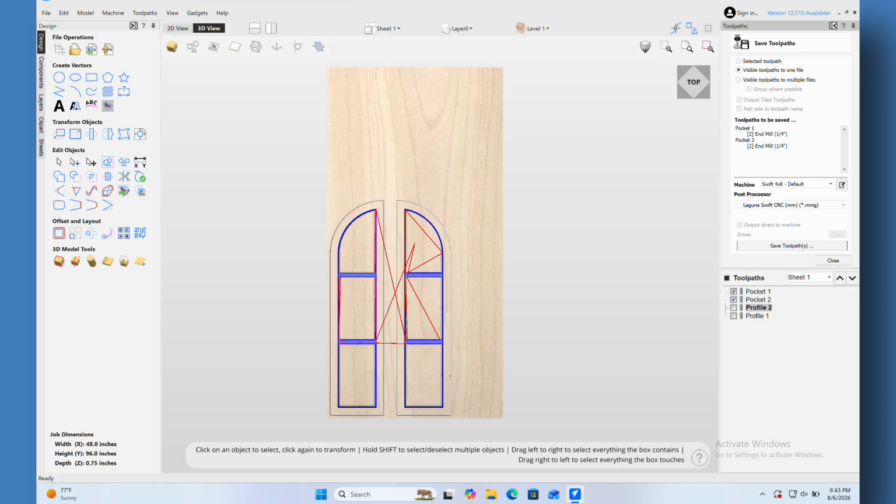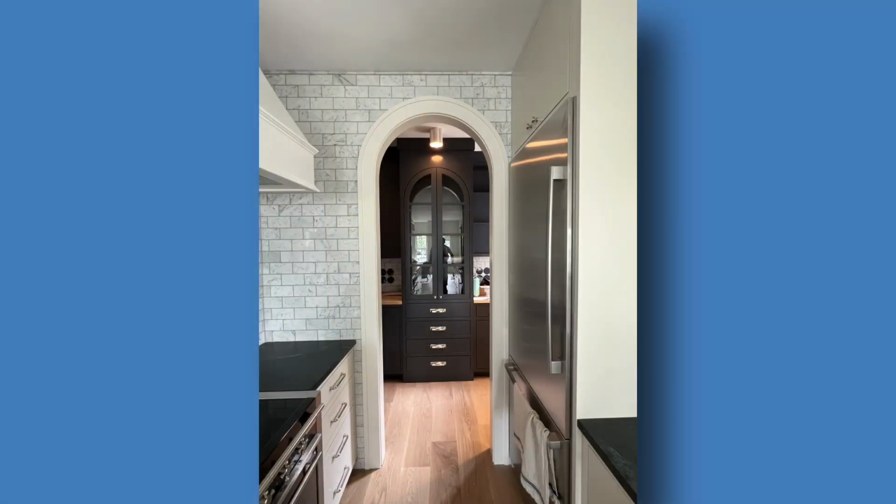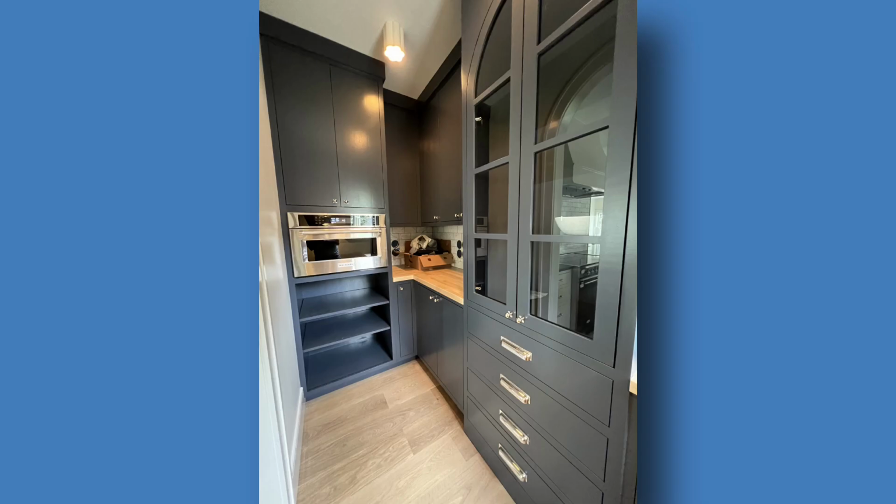The homeowner ultimately decided to go with 3 mullions instead of this design. If you'd like to add more evenly spaced mullions, simply type 4/ instead of 3, then repeat the remaining steps. It's an easy way to create as many evenly spaced openings as your design requires. Here are a couple photos of the finished doors after installation.